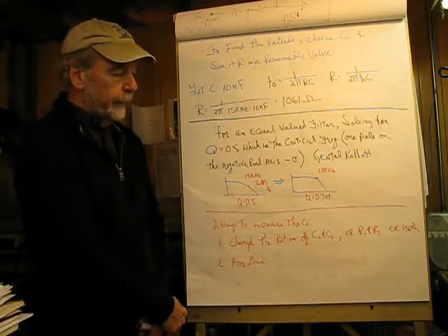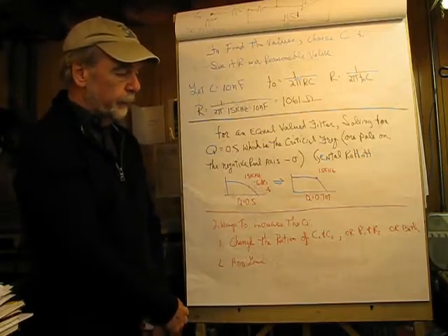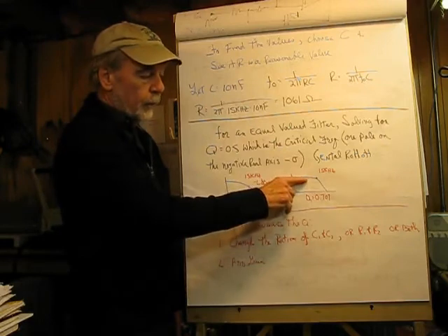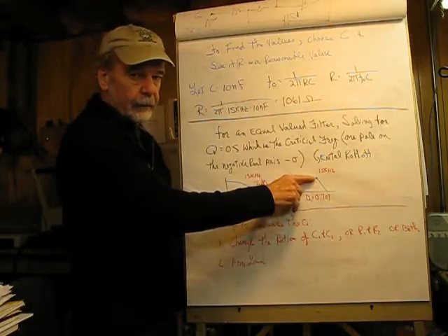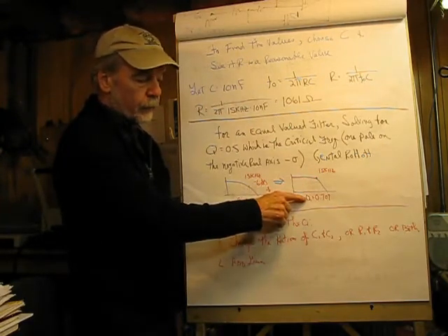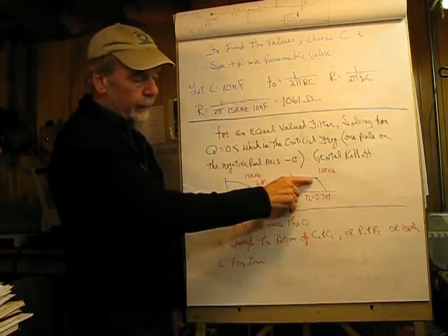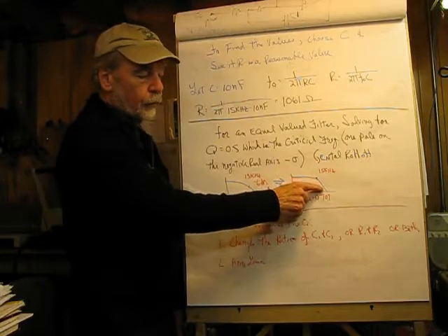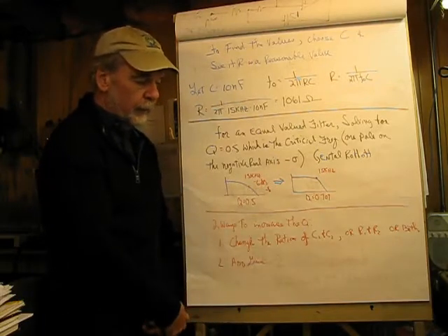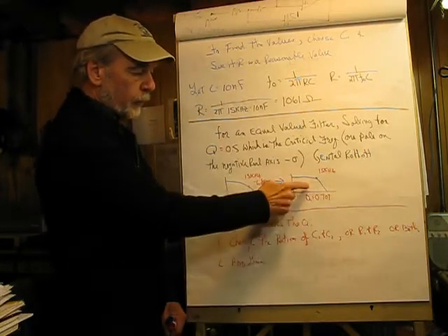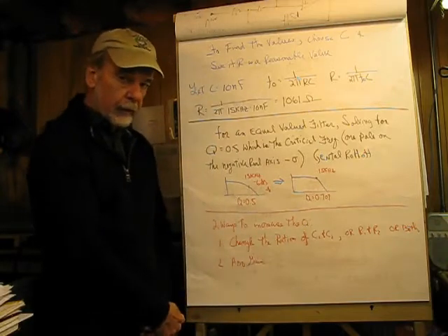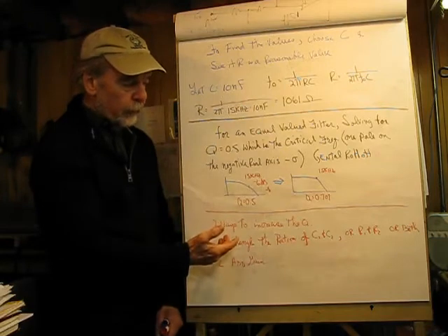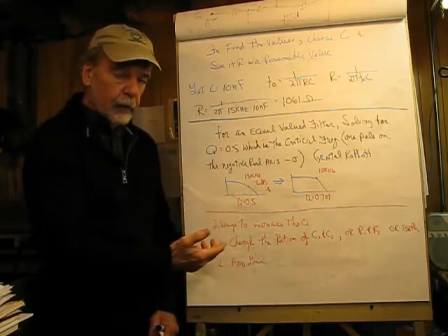Now if we adjust the values a little bit and pump the Q up to 0.707, what we see is maximally flat, and this is standard with Q of 0.707, maximally flat out to the corner frequency, which is 15K. Then it goes into a roll-off of negative 40 dB per decade. This configuration is so popular it has a name, and the name is Butterworth. Different Qs, as we'll see later, are assigned different names.